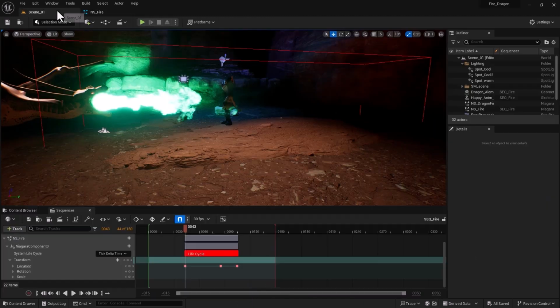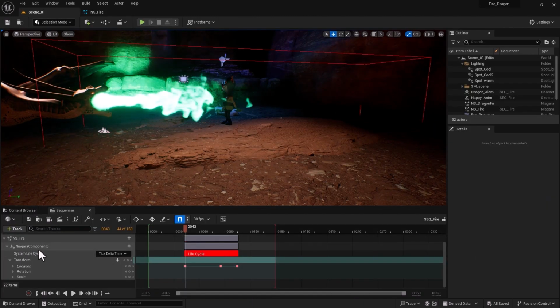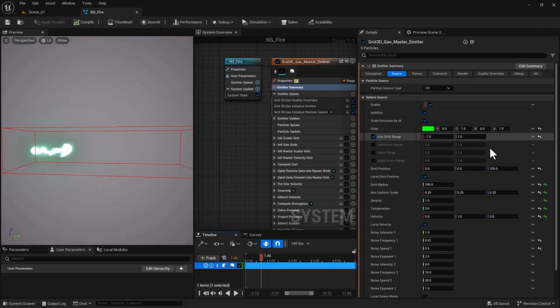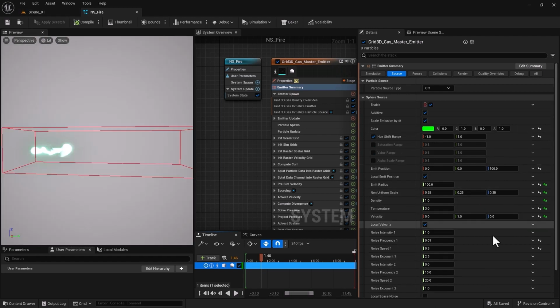And despite the fact that I have the Niagara system on my level sequencer, there is no level sequencer icon popping up right next to certain attributes, just like, you know, lights. When we bring in lights, we always get the camera sequencer icon when we can keyframe them directly from the properties detail panel. We don't have that option here either.